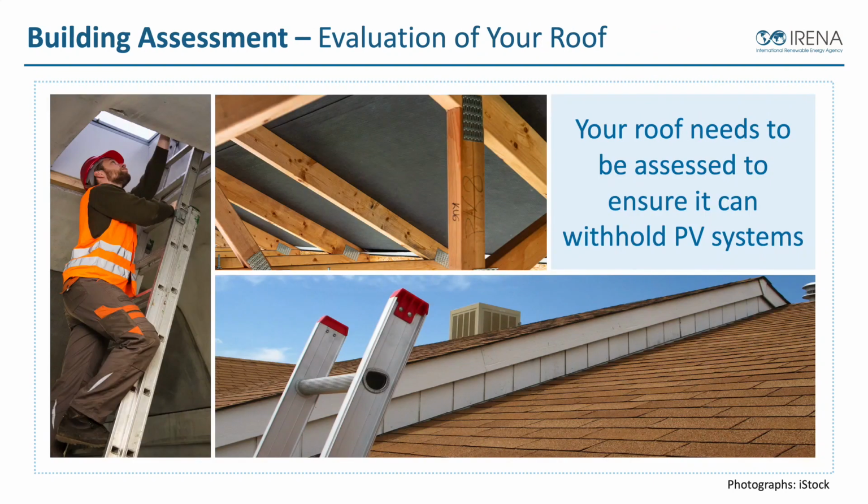The other thing when we're evaluating our roof is we need to understand the structure. So your roof needs to be assessed to ensure it can withhold PV systems. We're thinking about the weight of the system. Now, overall, solar is not really that heavy, but that's where it comes down to what's the quality of construction, what's it designed for? Are those buildings designed for heavy wind and storm or hurricane or typhoon type of wind loads, or are they really light built because the area where you live doesn't have big storms normally?